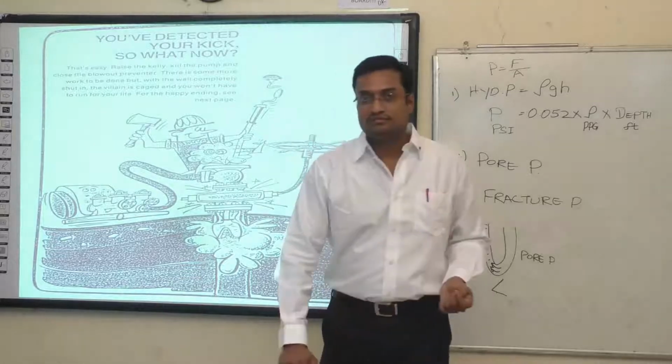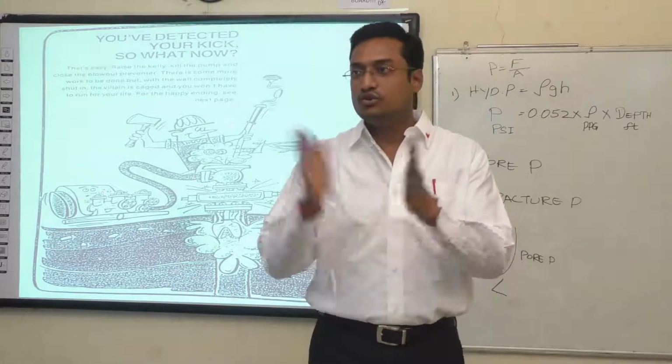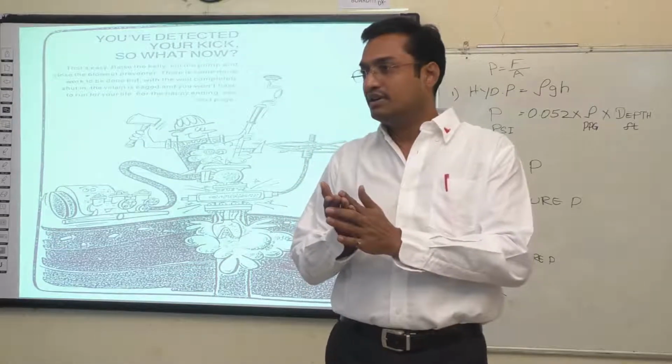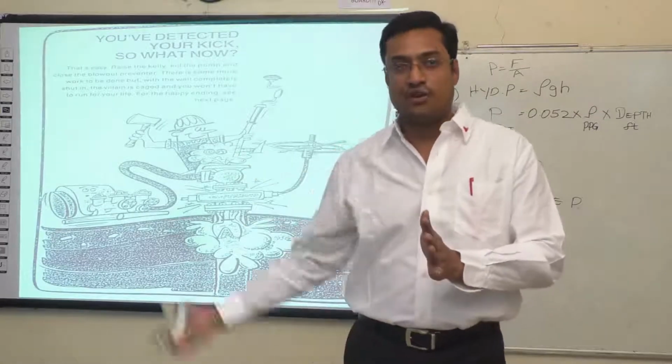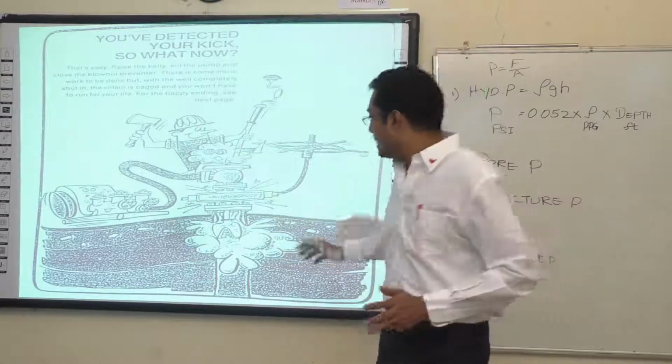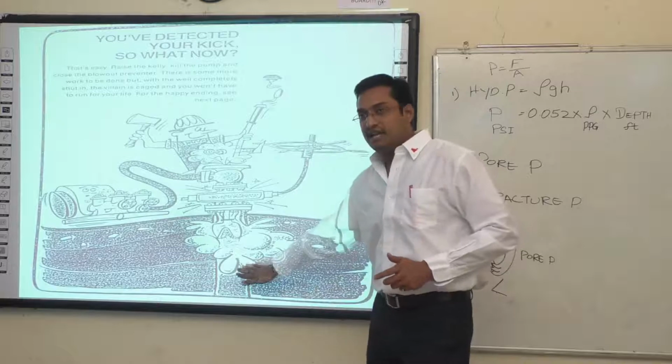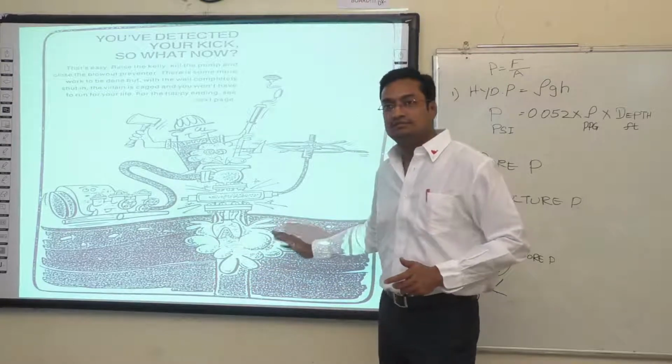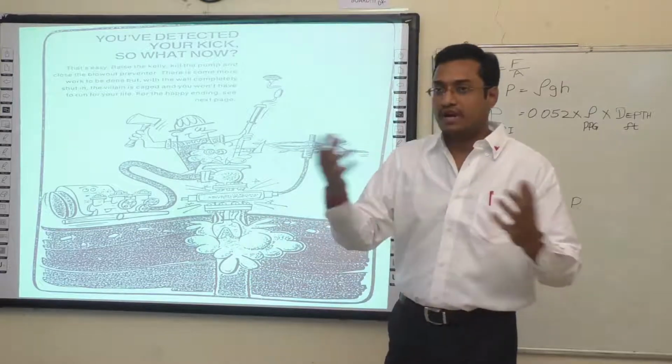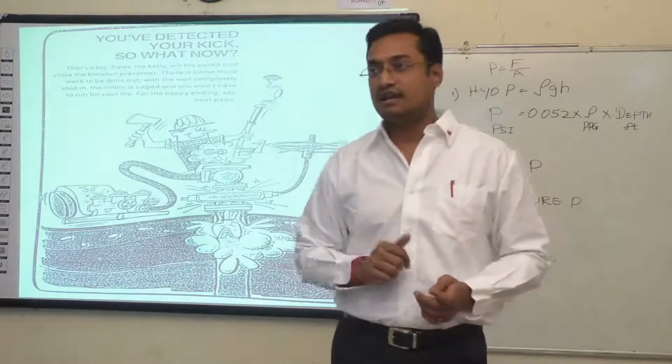What do you have to do? You have confirmed that you stopped the pump, but the well is still flowing out. That means the kick which has entered inside is pushing the fluids out without any input. You are getting output. That is a kick.